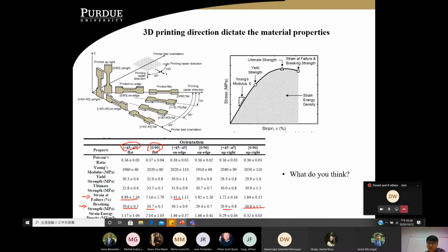It's simply a matter of how you originally design your components, the way the forces are applied, and how the 3D printing process and the nozzle used are not able to show the material's full potential. So when you design something and run a simulation model, you might get an output like 100 MPa. But in reality, you probably get half of it, 50 MPa instead of 100 MPa. So don't be deceived into thinking the material is not strong enough. It really depends on what material you select in the end.